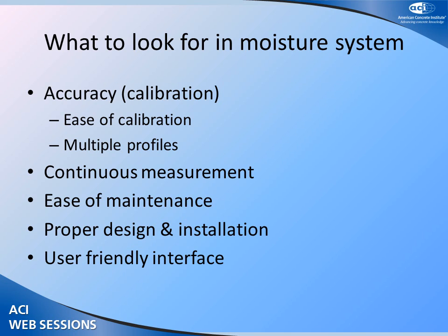Also, you need to see what's happening in the concrete batch plant to make sure that you understand how the operations of the batch plant, how the storage of the materials, how the charging of the hoppers is going to affect the variability of the concrete that's being batched, and the total moisture, the total water content that's being batched.